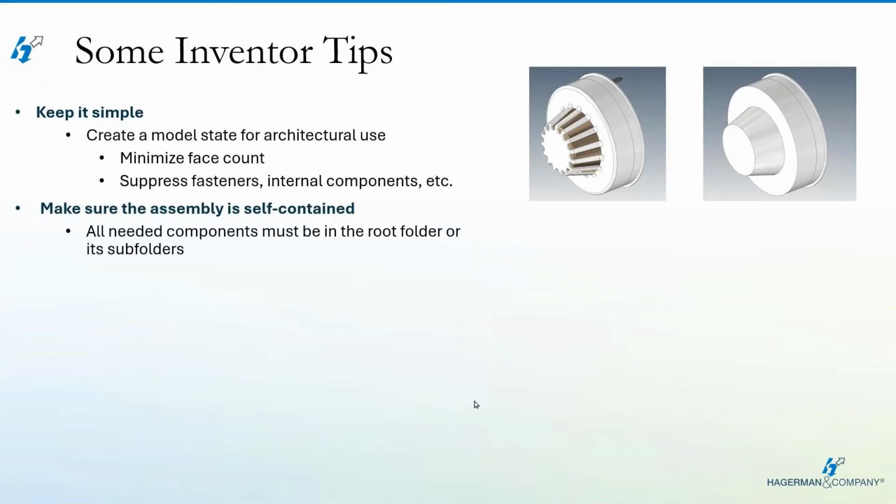I mentioned this before. Make sure everything is self-contained. So you start at that root folder. Everything that you need to have that assembly behave properly should be in that root folder or subfolders underneath that root folder. I think of the root folder as the tip of the iceberg. But again, not going outside to content center folders. Have them be local.